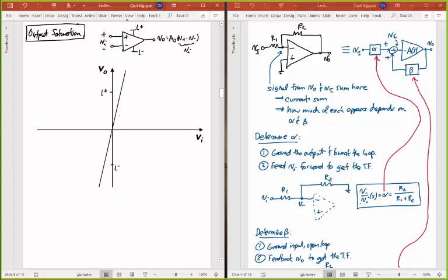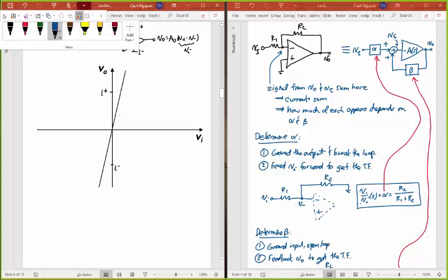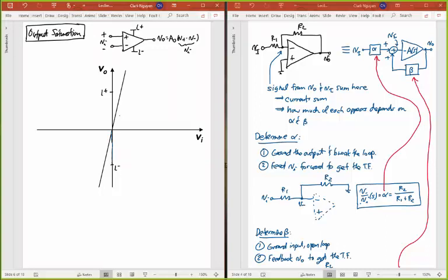And so I'm going to do the same thing that I did with that other discussion. I'm going to go ahead and stick in an input signal. And first I'm going to make an input axis in blue here, where that's time. Okay. And then in this direction is going to be my amplitude. So that's VI, my amplitude. Let's say I have an amplitude this big that I'm putting in to my VI. Well, let's first put a reasonable amplitude in. Okay, so if I put a reasonable amplitude, and usually that VI is going to be very small because feedback will ensure that it is. And so if this is my VI, just that big, then I can draw in its sinusoid as this.